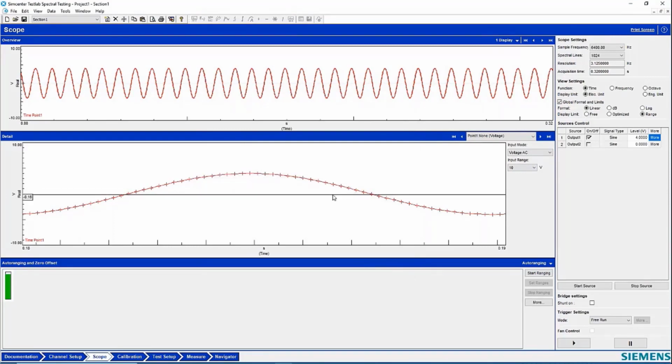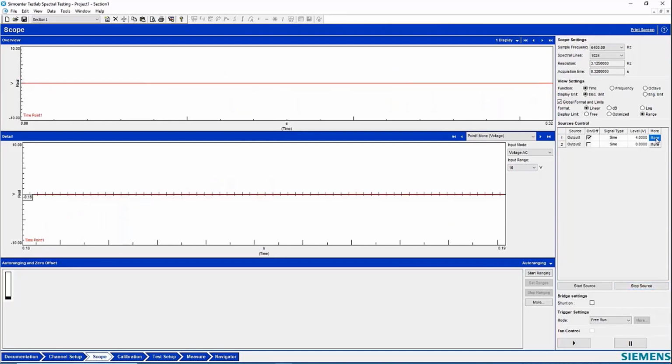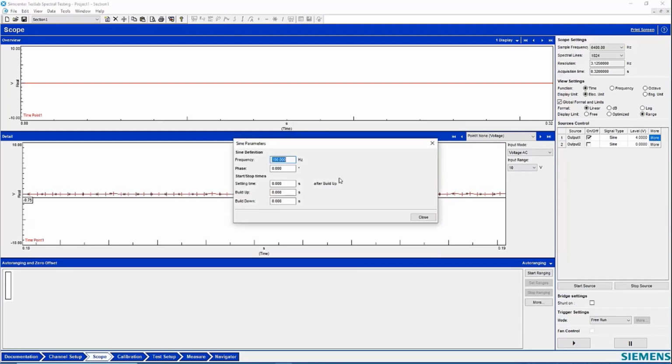Yeah. So if you can see there's like a little cross here, there should be 64 of those per second. And it does look like a nice sine wave. Now, I think what Charles is talking about, we have to be careful about when we set our sampling rate, because the way the computer shows this is a little misleading. It connects the dots with a line. So we think we might have a continuous wave, but really it's made of discrete bits or data points.